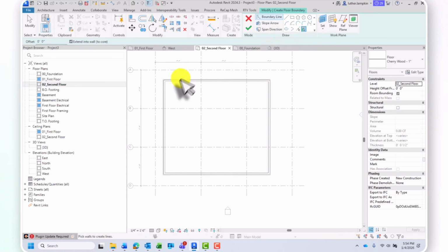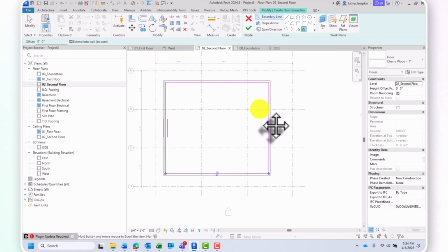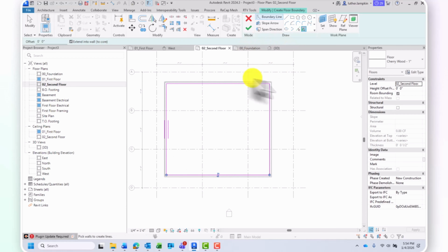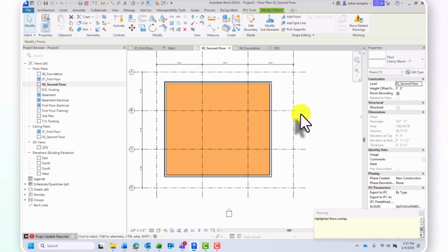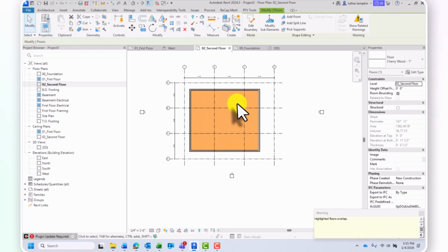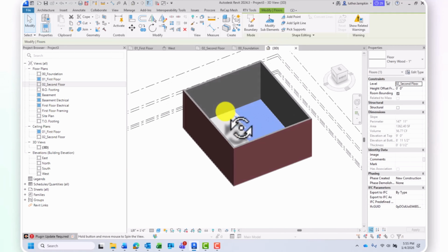And now I'm going to do this again. I'm going to do inside. And as you can see, it's starting to select the inside of here. All right. And now watch this. So now that that's all said and done, it's telling me that it's room bounding. All right, and I'm going to say cool, boom. So what did I just create? So now I just created, you see, look, I've got my slab.